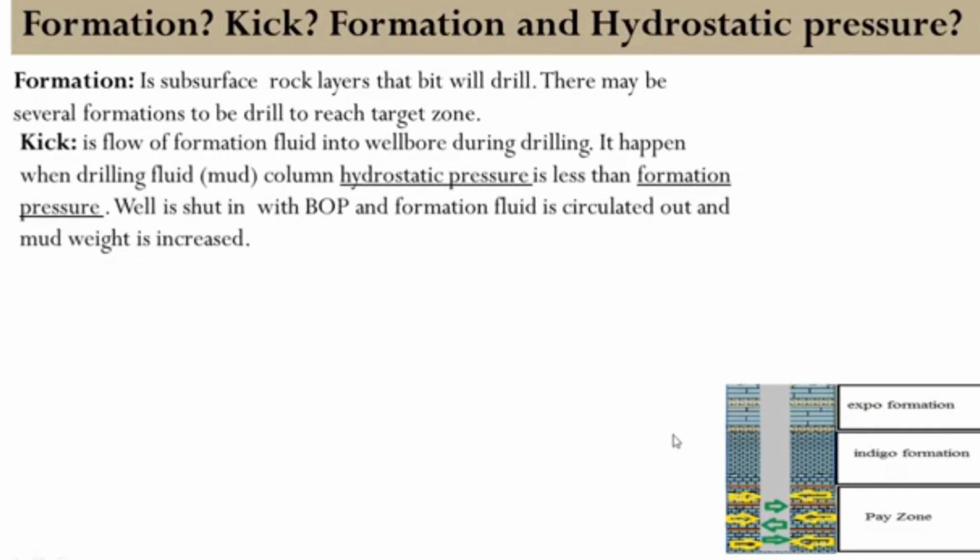Kick. What is kick? Kick is the flow of formation fluid into the wellbore during drilling. It happens when the drilling fluid or mud column hydrostatic pressure is less than the formation pressure. The well is secured with the BOP. Formation fluid is circulated out and mud weight is increased.